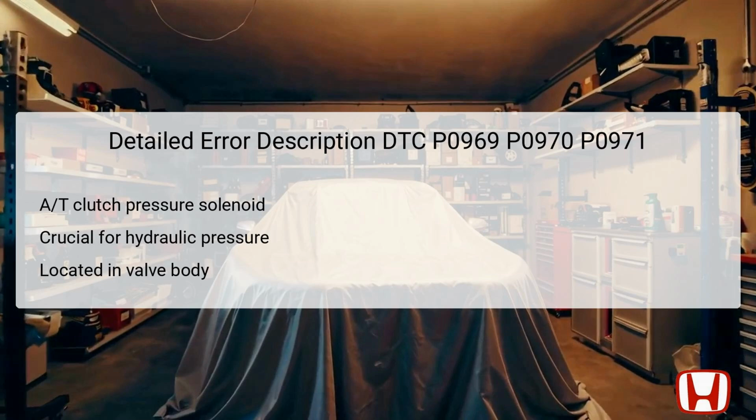The solenoid is housed within the valve body of the transmission, making its access somewhat challenging, as it often involves disassembly. The diagnostic issue arises from electronic signals that control the solenoid's behavior and can lead to subpar transmission performance. Lack of proper functioning can lead to failed shifts or erratic transmission behavior, serving as critical indicators to further troubleshoot. The specific codes P0969, P0970, and P0971 provide detailed performance feedback, allowing for targeted diagnostic steps.